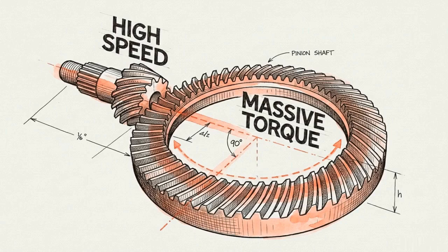This 3D vector model demonstrates the precise mesh between the pinion and the much larger ring gear. This forces the longitudinal power flow to take a sudden 90-degree lateral turn. Its secondary function is final torque multiplication. The massive size difference between the pinion and the large ring gear acts as a mechanical lever, drastically decreasing the output speed while proportionally increasing the turning force.